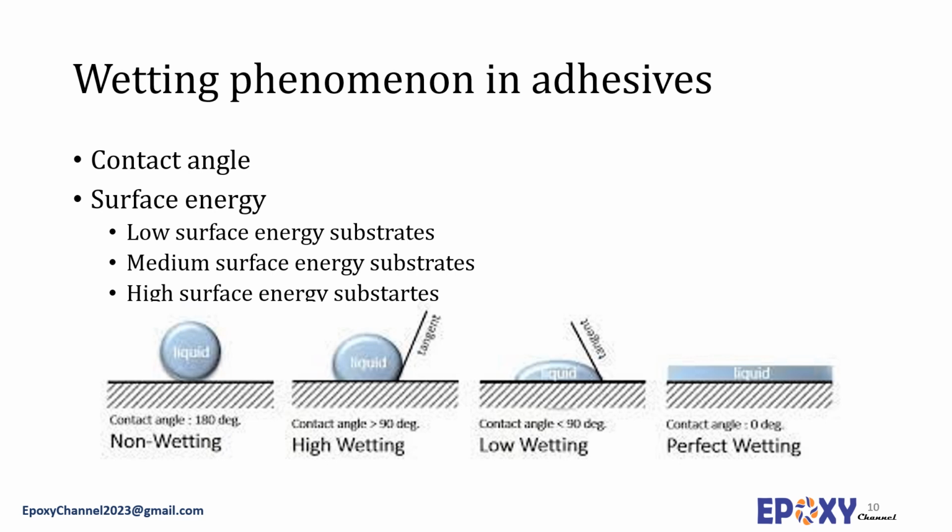Wetting, which is simply the ability of a liquid to wet a substrate surface, significantly influences the strength of an adhesive joint. It is quantified in terms of the contact angle, which is the angle the liquid, here the adhesive droplet, forms when placed in contact with a solid surface. The contact angle can be related to the surface energies of the two contacting materials. A schematic of the contact angle has been presented here.